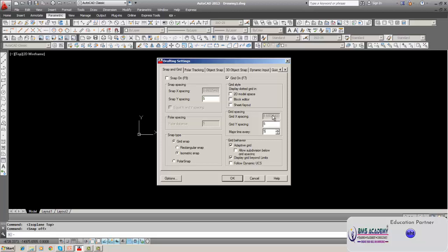Original drawing scale, suppose it is 100, then the isometric scale is 81. So suppose the 100 line is inclined forward at 45 degrees, then it becomes 80% of its length, the projection. It becomes the projection in the vertical plane. If you know a little bit of trigonometry, you will understand all these things. For the time being, I will not go into detail of its length and other things.